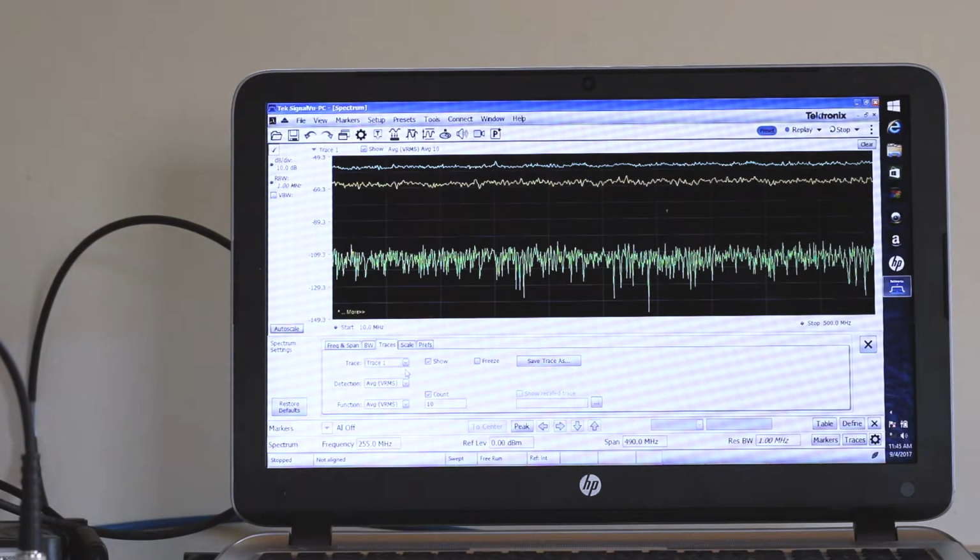With cabling in place, press the on button in the demo board. LEDs throughout light up, indicating that the demo board is prepared to output signals to the connected RSA306B spectrum analyzer and through it to the PC. Set reference to internal. Set the run mode to free run. Click the row and column buttons to select OFDM to determine the demo board output. This completes the procedure for configuring the demo board.